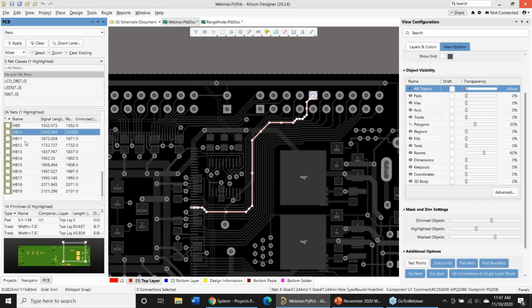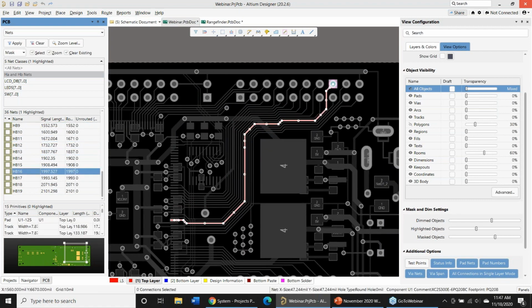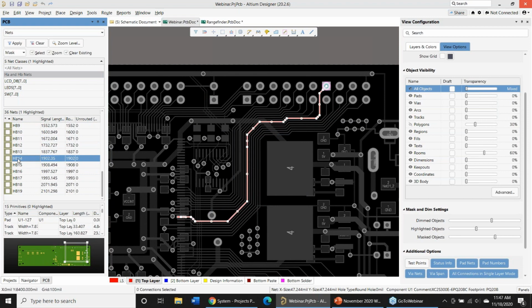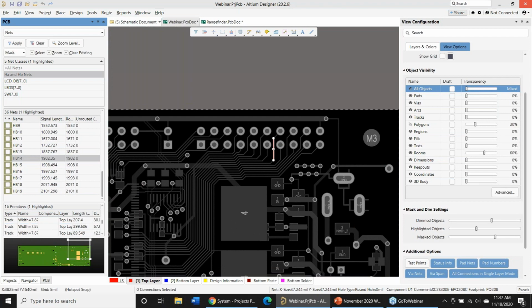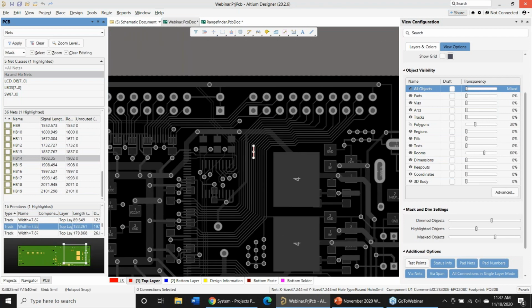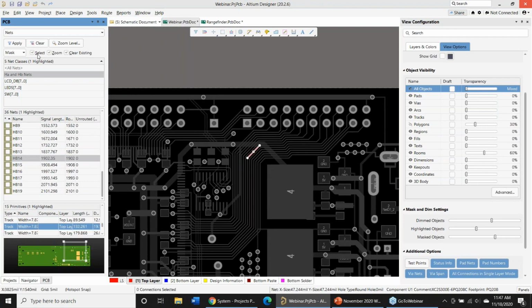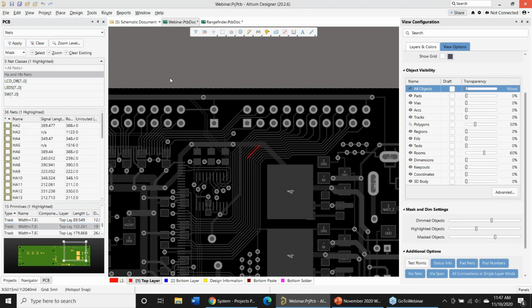So now I can pick each one individually if I want to. And once I pick each one, then down here you get each primitive of that pad. So this goes on and on and on. That's how the PCB panel is: class up here, members of the class, and primitives within those members. Okay, if I want to change a color of one of these nets, this is a nice way to be able to navigate later if you want to.